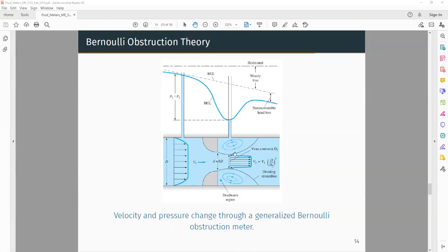So fluid tends to move from higher pressure to lower pressure. So fluid will move against the flow into this one and starts rotating arbitrarily and creating some eddy loss. These are actually the mechanism of minor loss. So we will have a portion of fluid rotating, and actually this is the minor loss, and this fluid is getting energy from the flow.